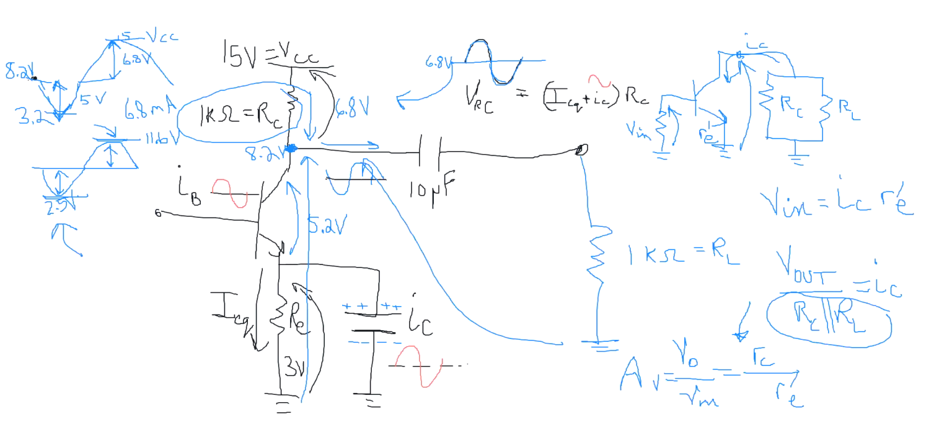So if you were to look at the new load line, adjusted, here's my DC load line, and it stops at VCC at the bottom. Remember, this is the voltage across the emitter and collector of the transistor. It can't get higher than VCC, and the current through that section to the collector can't rise above the saturation current that I calculated before with just RC and RE.